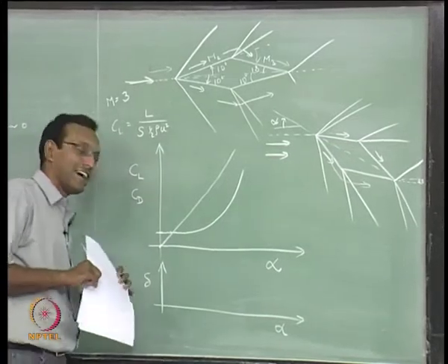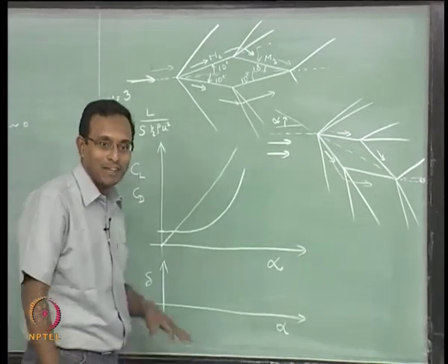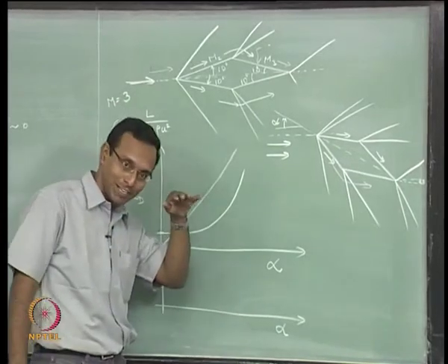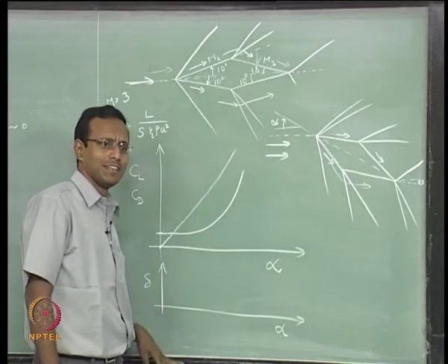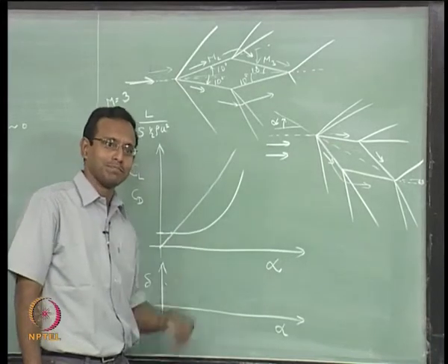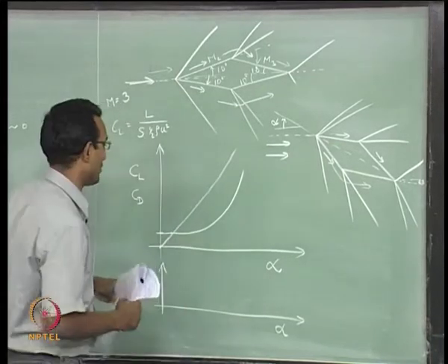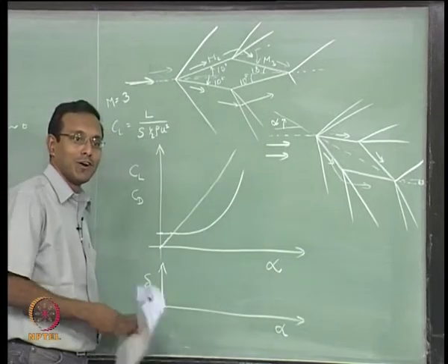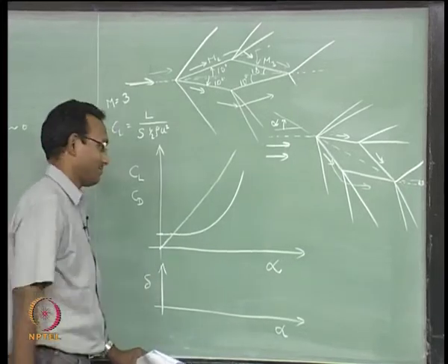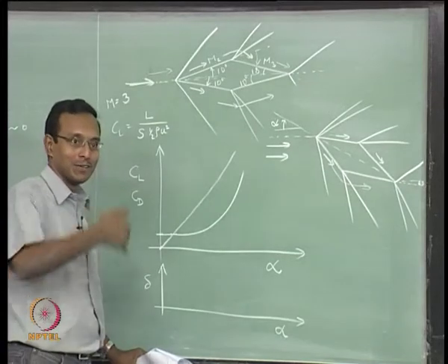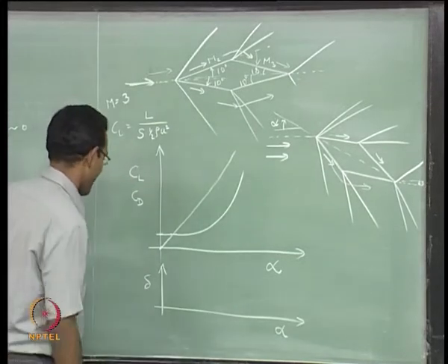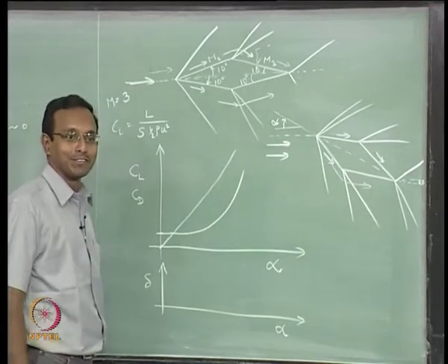Okay. The way I think about downwash is like you are climbing stairs. What do you do? You kick that particular stair down so that your body goes up. That is what the airfoil is doing. It is kicking the air down so that it goes up. That is lift. This is the way you think about it when you talk Newton's laws. Same Newton's law working here. The airfoil is kicking the air down so that it goes up. Okay. That is action and reaction if you want to think about.